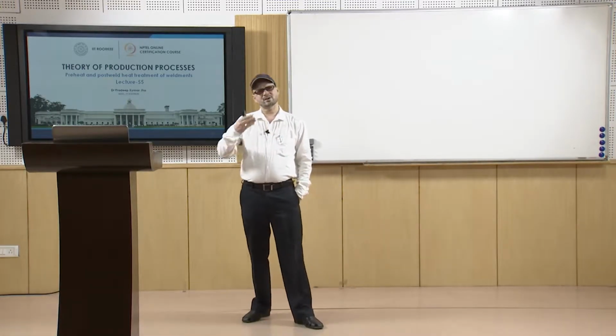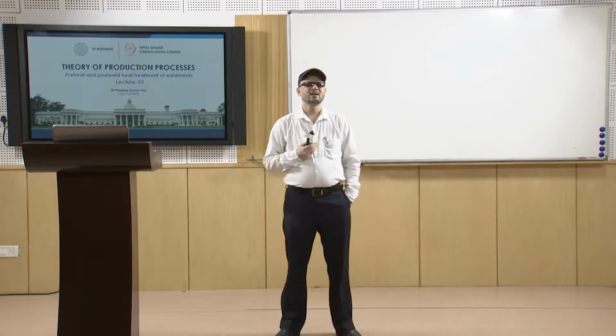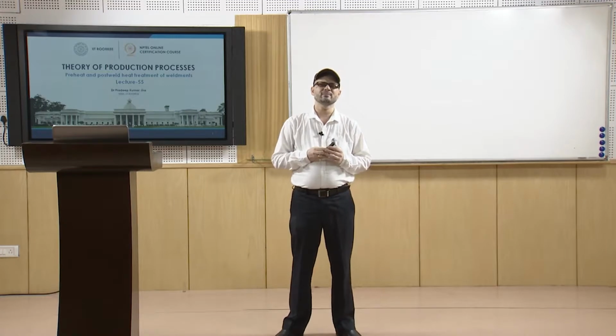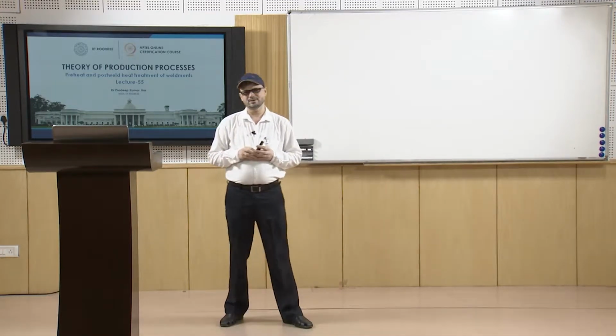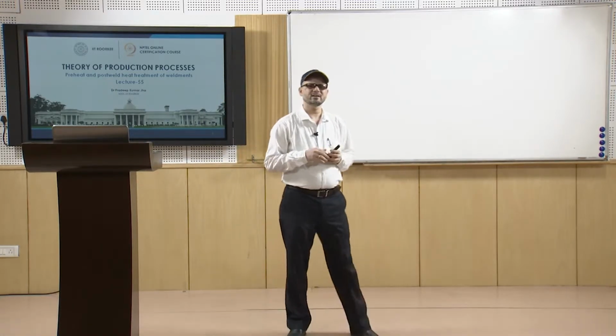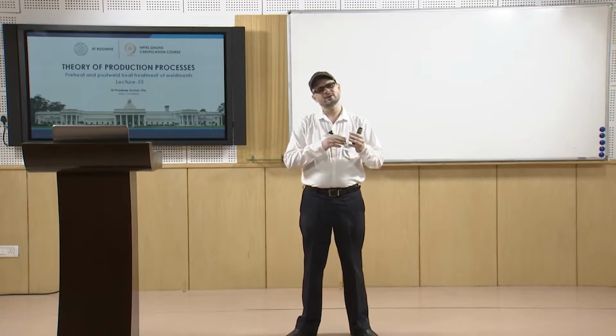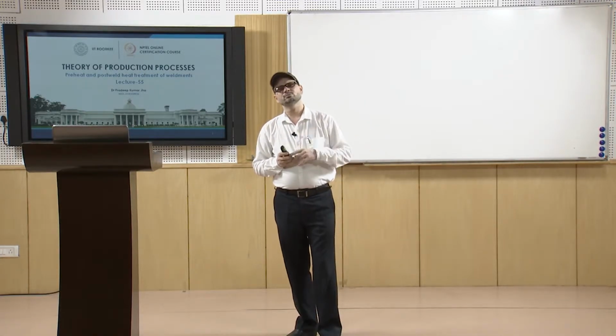This is primarily about preheating, and then we talk about post weld heat treatment. In post weld heat treatment, the primary aim is stress relief treatment. In many cases the stresses generated are quite high. So for relieving the weldment of the stresses, we do this post weld heat treatment.